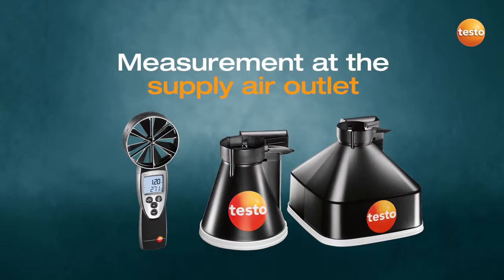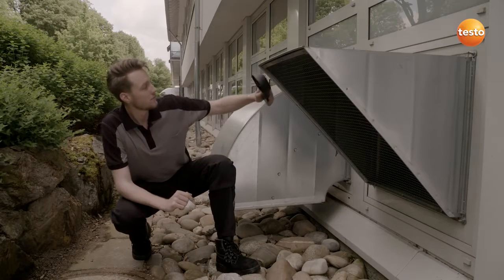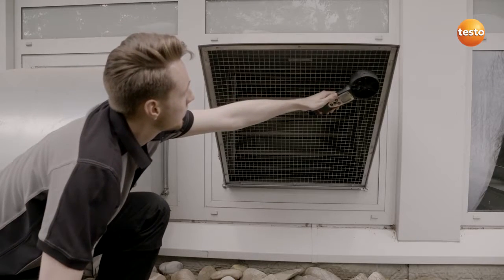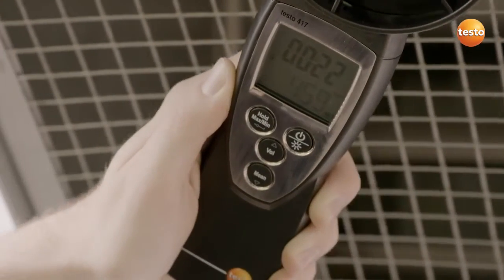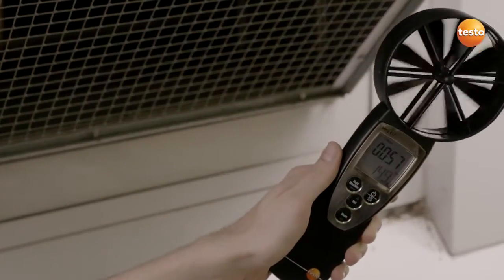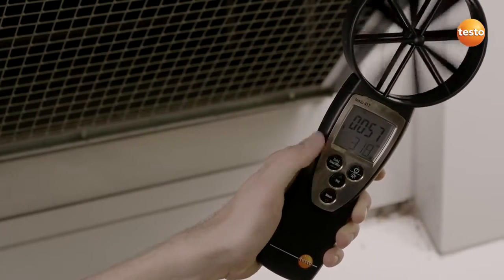This is how you measure properly at the supply air outlet. When measuring at the supply air outlets, take into account that different flow rates occur at the outlet area because of the air outlet grill. This is why the vane is moved across the ventilation grill in loops. The Testo 417 automatically generates a timed mean value.